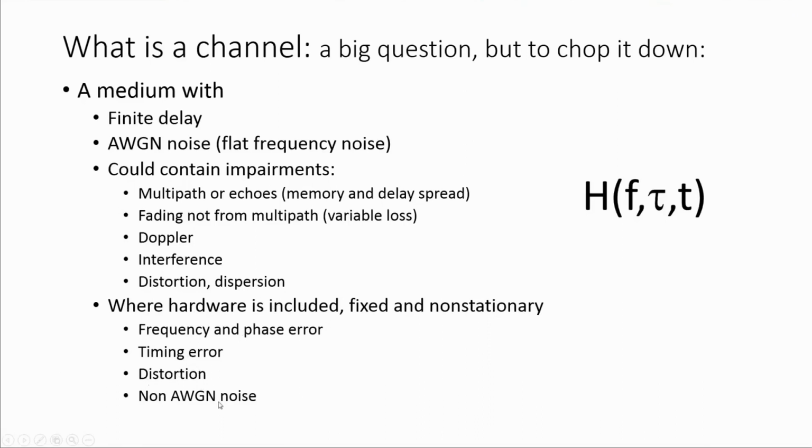And then non-Gaussian noise, which is colored noise or phase noise, 1 over F noise. All those things are synonymous. So this is a statistical phenomenon that's often not addressed in things that you'll find online. So all this stuff can be lumped together into a transfer function. If it's a wireless channel, it can be a linear transfer function, which is very handy for computation.